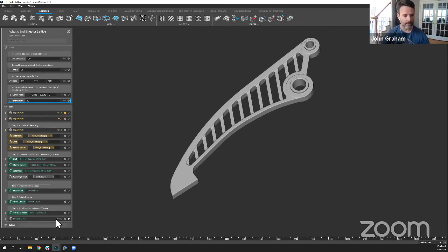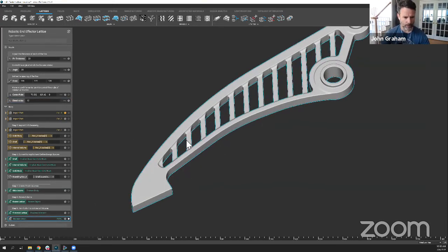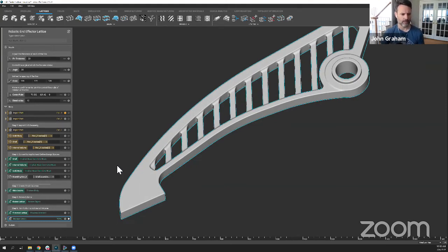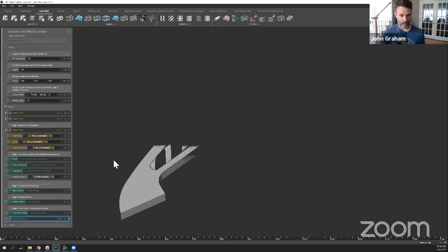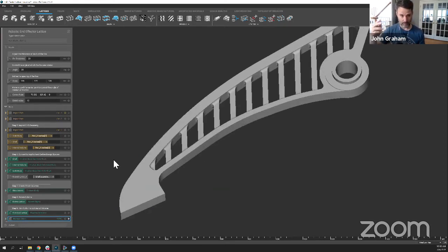One thing I want to draw your attention to, and we've shown this on several demonstrations, is that you tend to get, as my understanding is, a lot of delaminating, if you will, of the lattices to the skins. One way to get around that is to put some radii between the lattices and the skin. Well, we automatically do that when we merge or blend things together, and I've gone to a higher resolution rendering so you can see that effect.